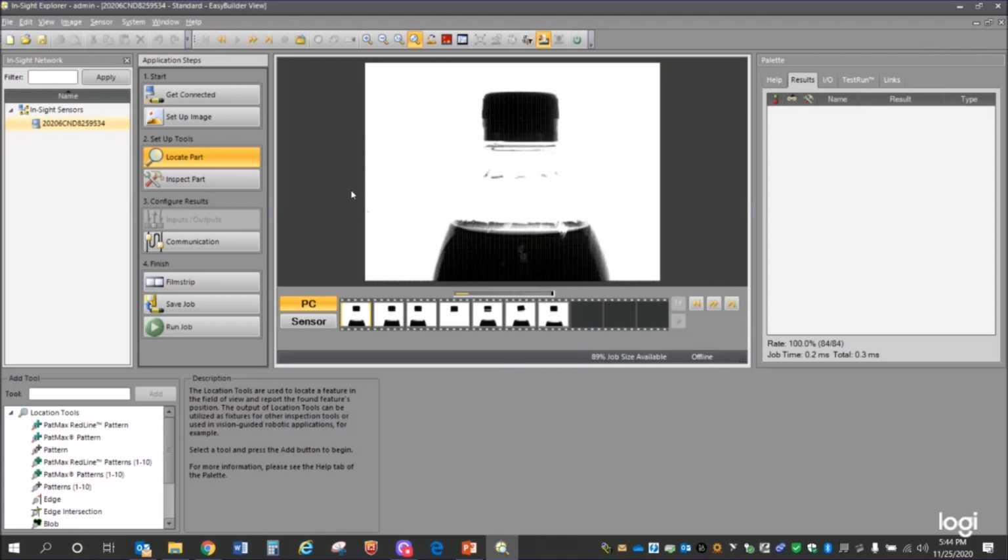So the camera is very specific. If I'm going to measure the level of something, I have to have a datum. What's a datum? Starting point. Yeah, it's like, if we're talking about a vise, it might be the fixed jaw of a vise, right? That might be our datum. Or if we're talking about calipers, it might be the fixed jaw of the calipers, right? That's the measuring reference to which we measure everything, right? So we need that datum in a vision system as well. So what we're going to do is we're going to locate that part.